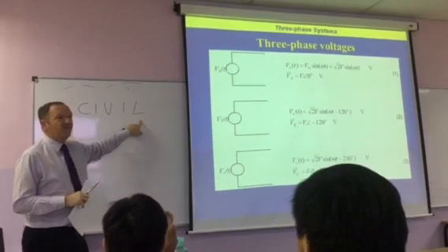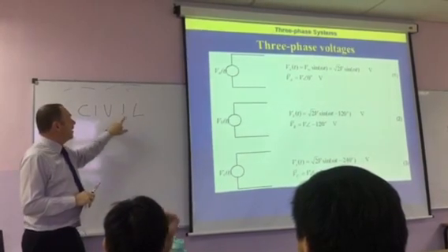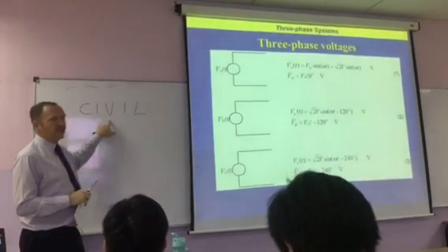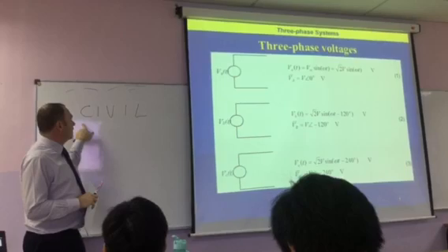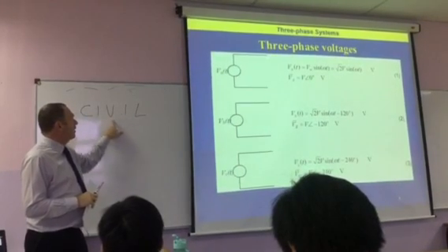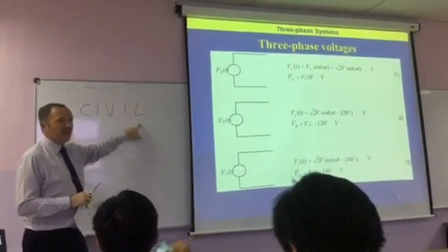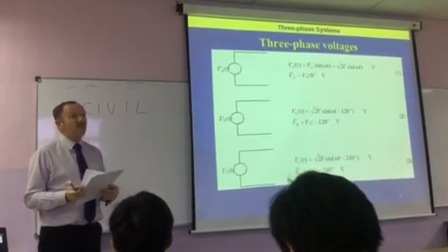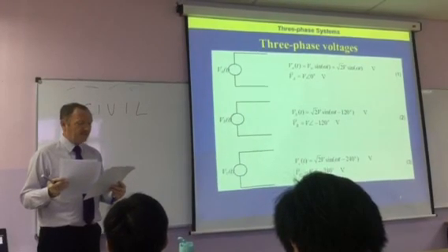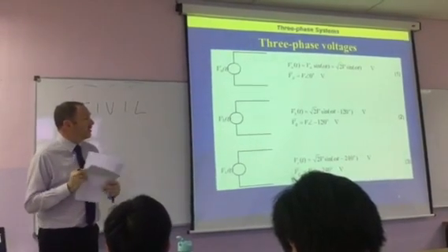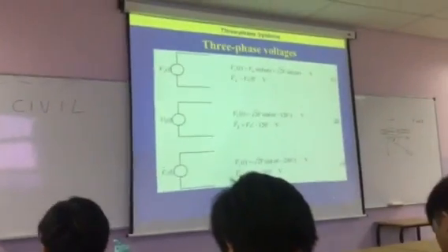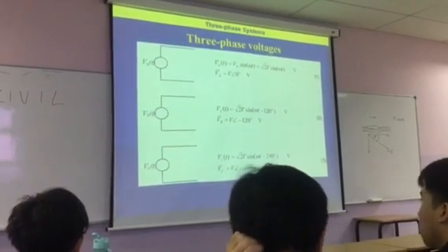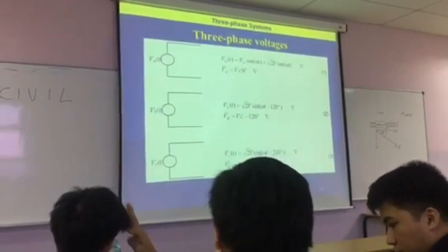If you have an inductive network, the current lags the voltage. So it's current leading for capacitance, current lagging for inductance. It's important to recognise that, because it can make a difference whether it's current lead or current lag. We normally represent lagging by a negative sign, and leading would obviously be positive.